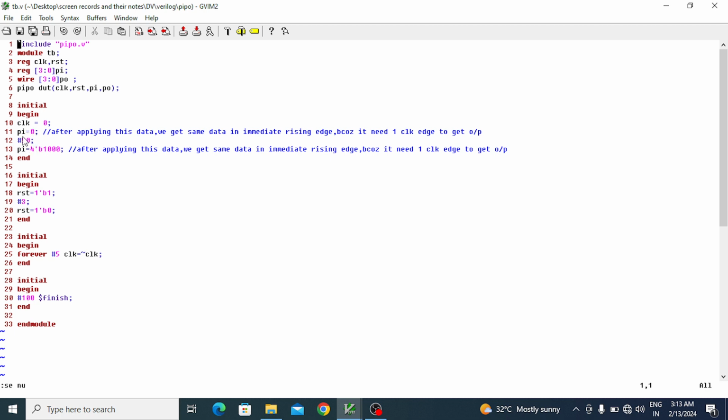But in previous lectures I wrote this input generation separately in a separate procedural block, and the forever I wrote in this block only. Either you can remove this here and keep everything in one procedural block, or write it as in the previous lectures.